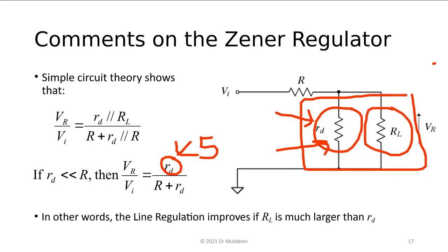And the normal resistors that you have are quarter watt resistors, half watt, 1 watt, and so on. The wattage rating tells you about it passing current. Remember, you pass current through a resistor, it's going to dissipate heat at I squared R. Once it's passing current, it has to dissipate the heat. It doesn't have a choice. If you put in a quarter watt resistor, can it dissipate it? Are you asking it to pass more heat than that? If so, it's going to get hot and it's going to be destroyed. So all of those things go into the mix, right?